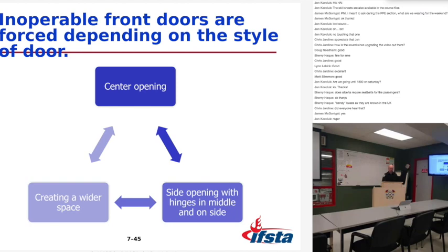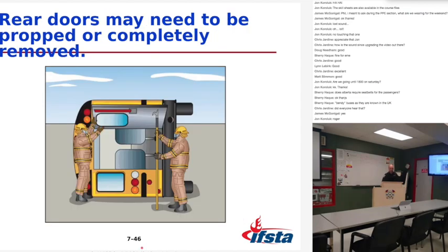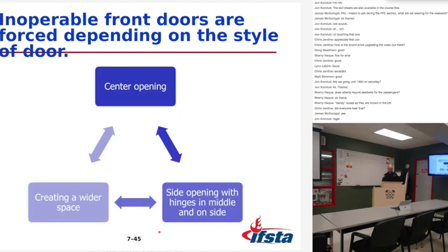Cut through a post at the top of the windshield opening. That'll give you the whole windshield and the door. Make relief cut in the bottom of A post at floor level. Insert a ramp between A and B posts parallel to the ground at top of the dashboard level. Extend ramp to push the wall forward. That really helps.